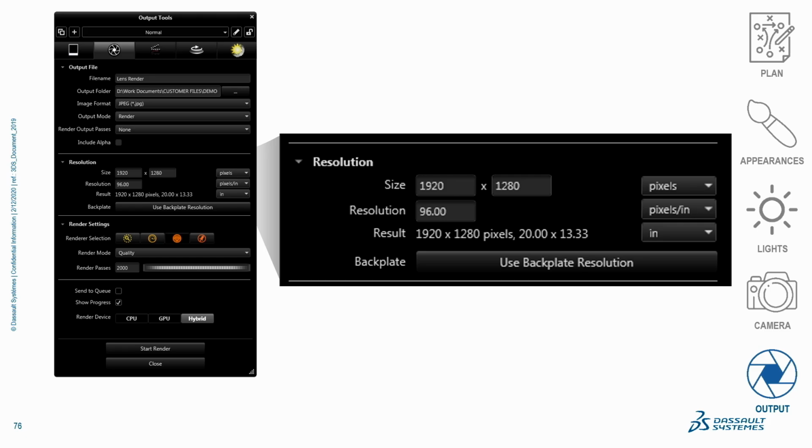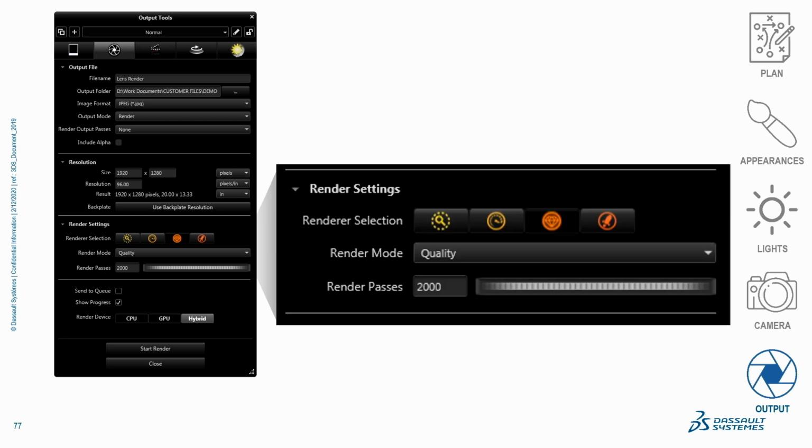Resolution underneath that gets a little confusing because the resolution actually doesn't really mean that much. The actual pixel size is what's driving the size of the image. I set this to 300 on mine and I just leave it. The only thing that it does is just how Photoshop reads the file in the end. It still makes the same size image no matter what. So it's not super critical that you need to know that. Okay, so once you get the resolution set, we just need to know the quality settings.